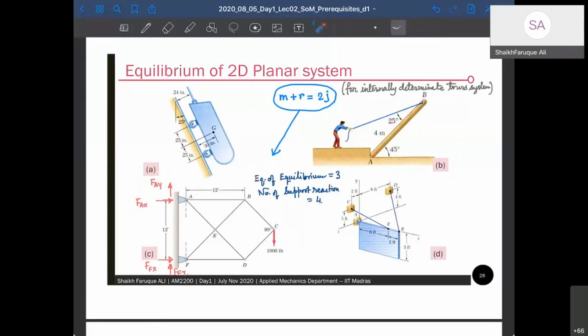I hope. Sir, we know for the point B, the forces should be same, right? So FE and EB should have the same force. There should not be any change. So I guess we can remove that point B and then solve further. It will become determinate, right? Point E, sir. The middle of Point E. Because the force on FE will be the same as the force on EB, otherwise point E won't be in equilibrium. That's okay. So how does that help to solve? And then I think it will become determinate, right? No. You have 4 unknowns on the outside itself.